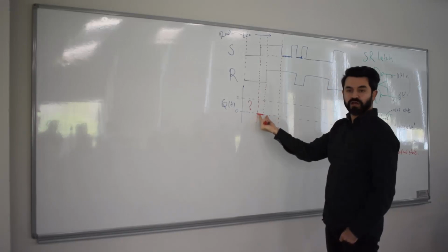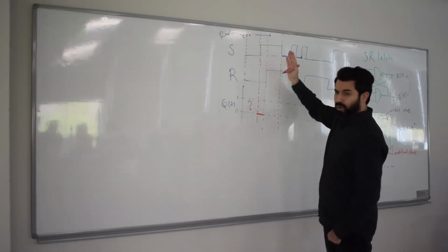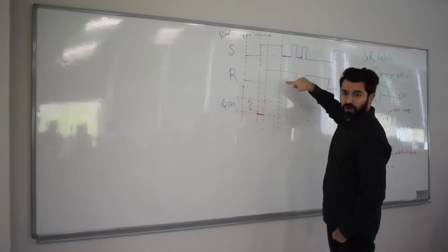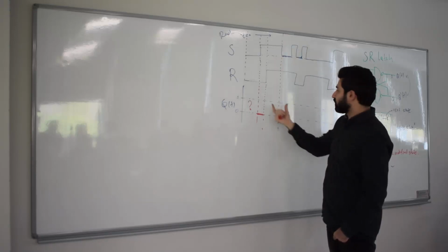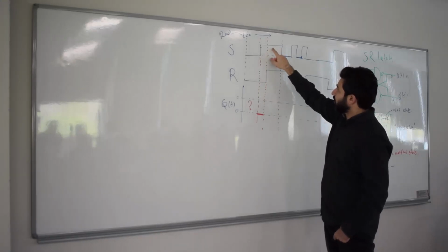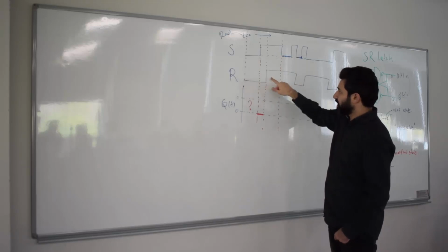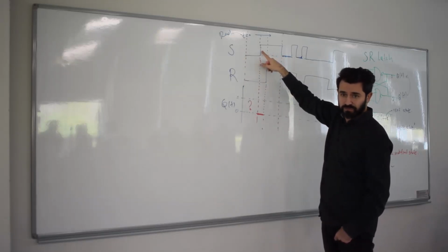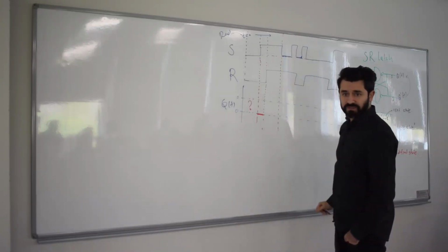This is a shorter time period, this is a bigger time period. The reason I'm dividing it that way is that whenever one of the inputs changes, whichever does so early, I clip the time to create another interval. Because in this time interval, either S or R makes another change. For example, R makes a change, although S does not, with respect to the previous time interval. That's why I clip the time.